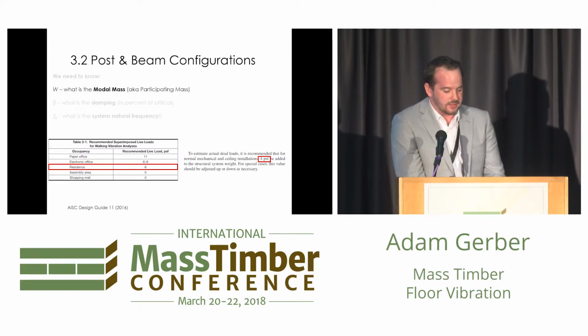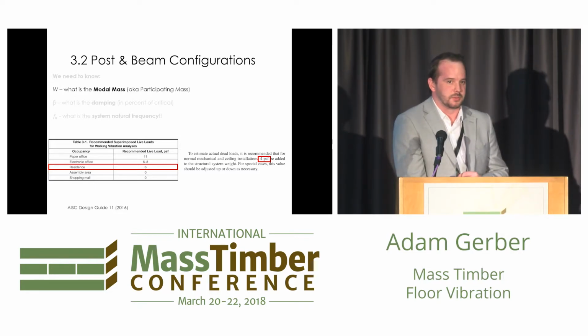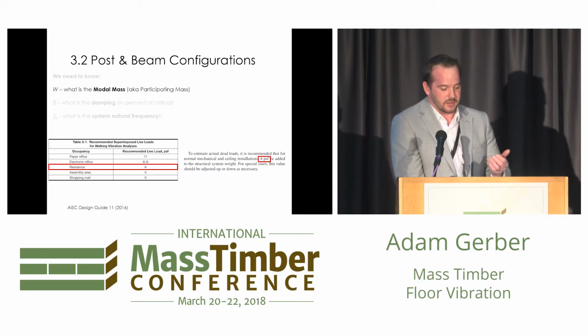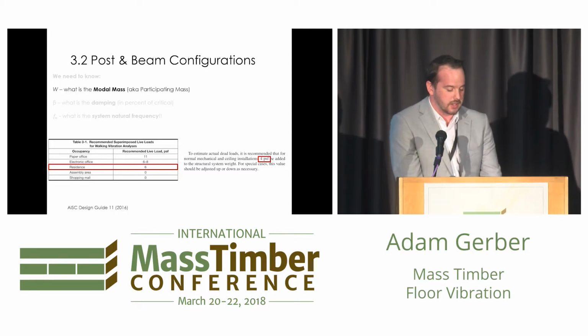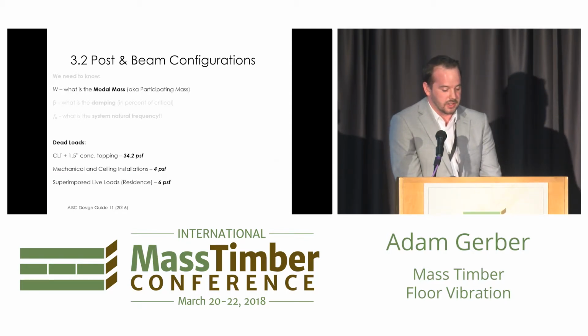So Design Guide 11 gives us a lot of good resources to help make a realistic estimation of how much load is going to be on the structure. It's definitely not full design load, it's not full superimposed load. It's a pared down version to best represent what you can expect to find in reality. So I think in this case for a little bit of live load and some suspended mechanical and electrical, they recommended combined about 10 pounds a square foot.